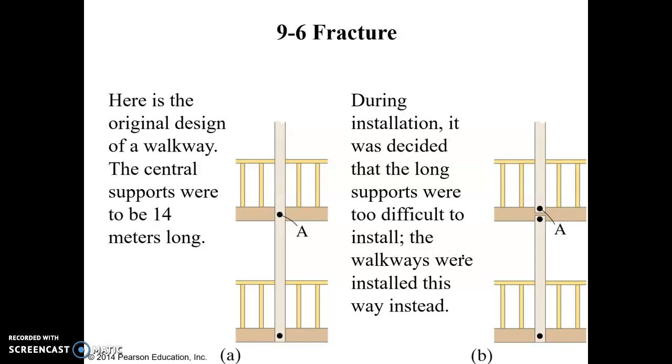Well, unfortunately, it didn't become apparent until it was too late. But the change that was made from one continuous tensile support supporting both of these walkways to breaking it up into two separate ones effectively doubled the amount of stress in the top one, and therefore caused failure. So it's an interesting application of physics in the world of structural engineering, and it's important to not overlook some of these conceptual things, or sometimes some really bad things can happen.